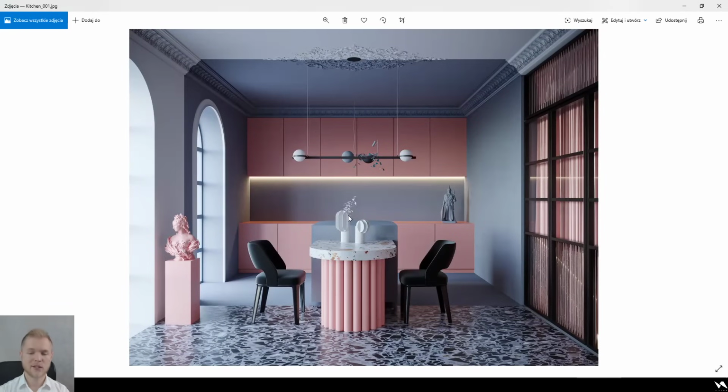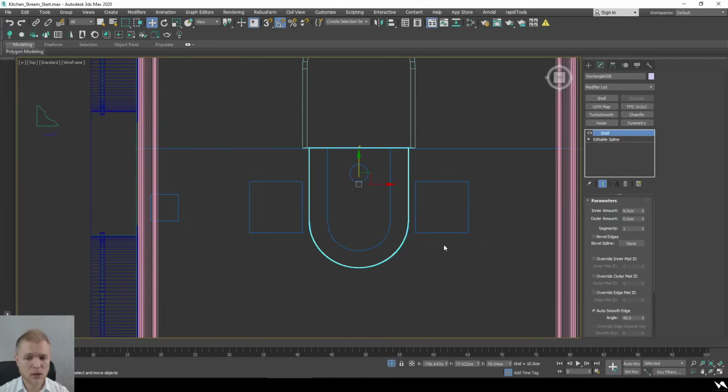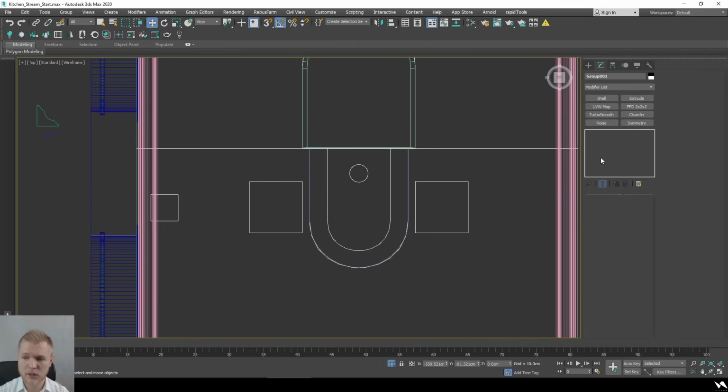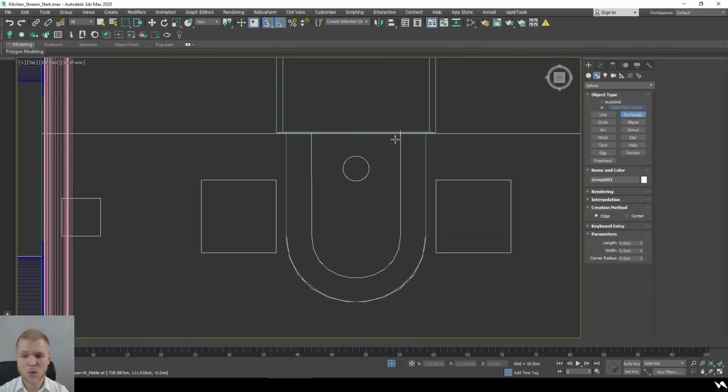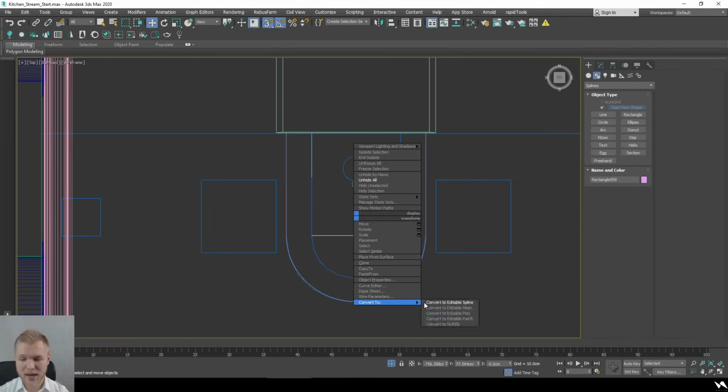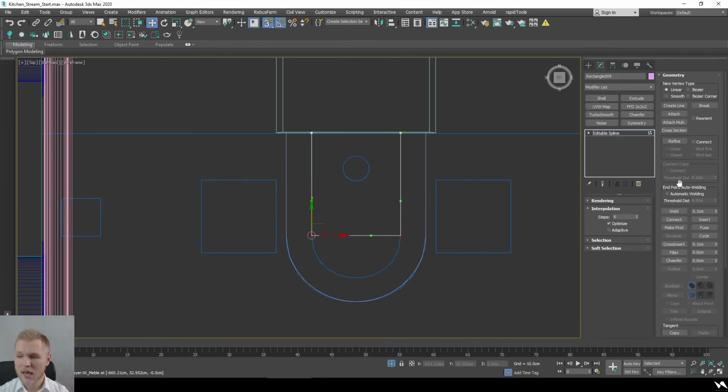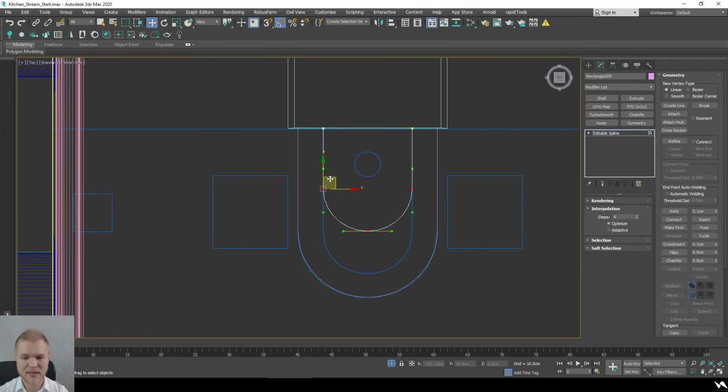Because doing this manually will take you a little bit of time, and it's always going to look a little bit sloppy. In Corona Renderer, we have a technique that is really useful, and you can check out our last interior webinar, which was about creating a hotel lobby. But this time we're creating something else, so we're going to use different techniques so you can learn something new. Instead of Array, we're going to use the Spacing Tool.